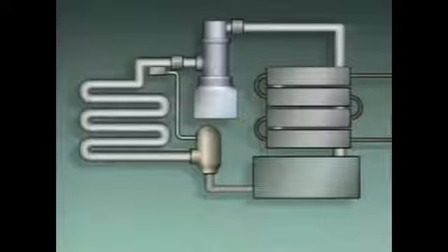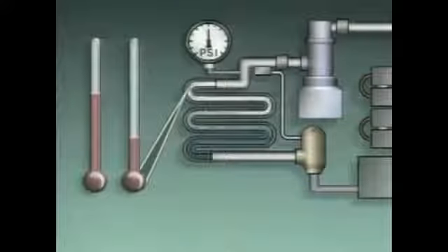As you may recall, the pressure exerted on the refrigerant in the compressor creates the flow through the system. Let's look at a refrigeration system that uses pressure switches to help maintain the proper pressures in the system. This system has a low-pressure cutout switch located on the compressor suction. It also has a high-pressure cutout switch on the compressor discharge. When the system is operating and the temperature of the substance being cooled drops, the temperature and pressure of the refrigerant entering the compressor will also be lower.